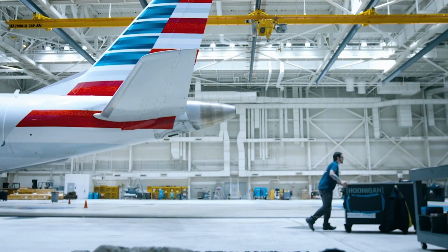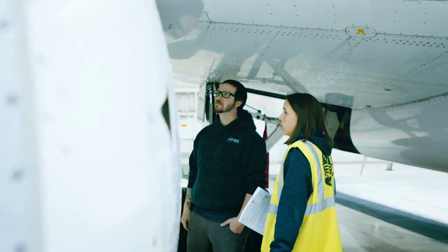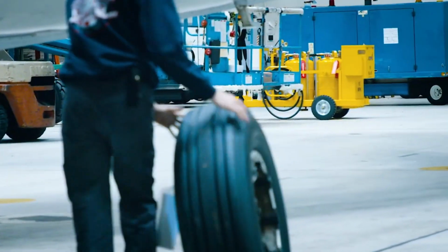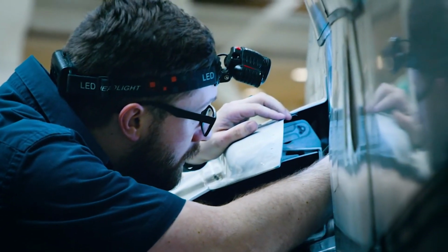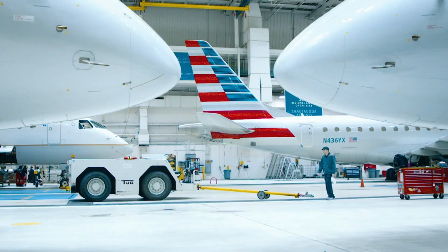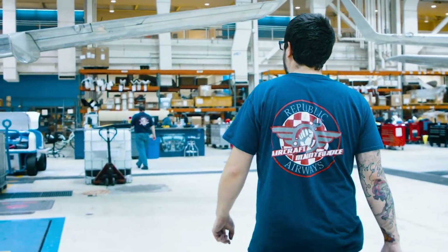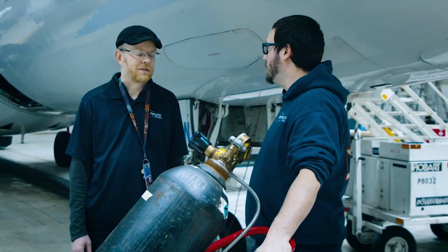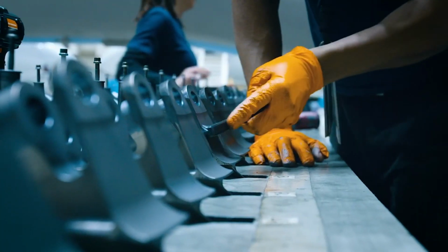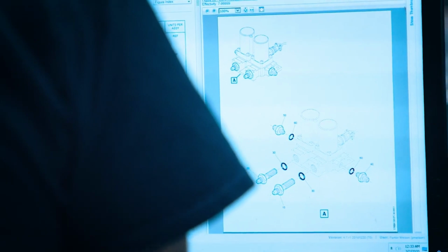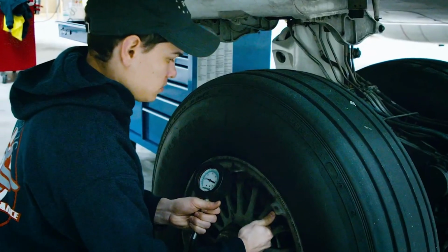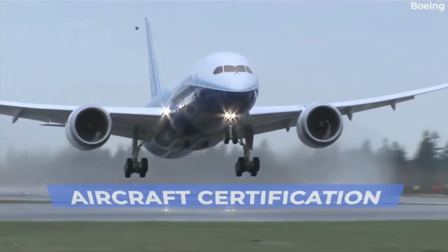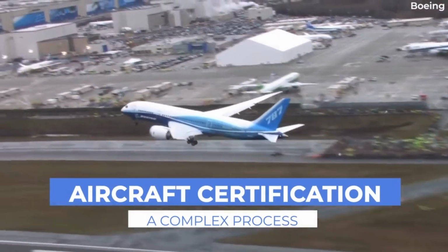A major change in the 9 or less aircraft maintenance requirements occurred in February of 2005 when Section 135.422, Aging Aircraft, was incorporated into 14 CFR Part 135. This new subpart, note the even number, to 14 CFR 135 specifically prohibits a certificate holder from operating certain aircraft unless the administrator has completed the aging aircraft inspection and records review. This inspection requires the certificate holder to show the FAA that the maintenance of age-sensitive parts and components has been adequate to ensure safety. This section only applies to multi-engine aircraft in scheduled operation with 9 or fewer passenger seats. It does not apply to aircraft operating in Alaska.